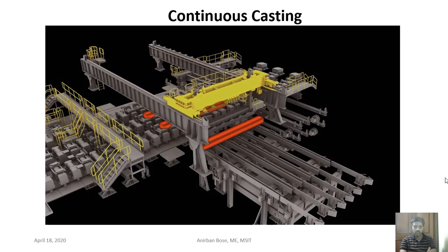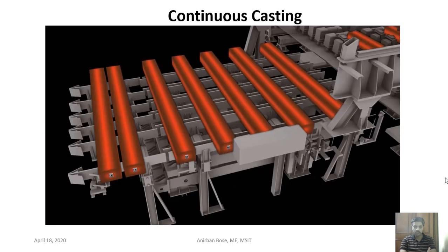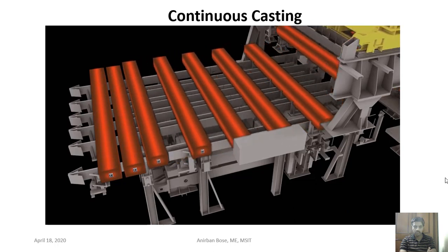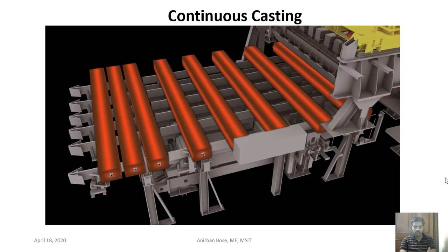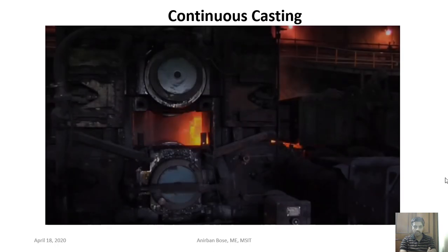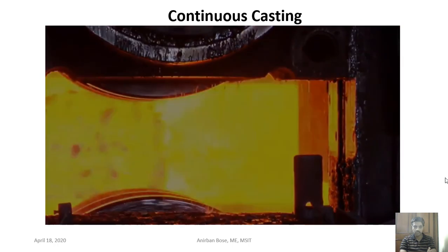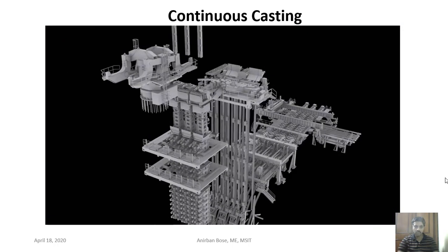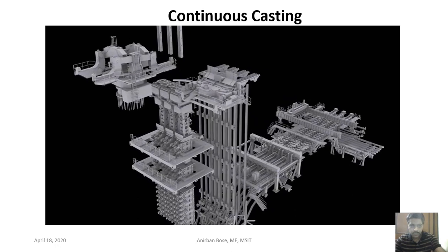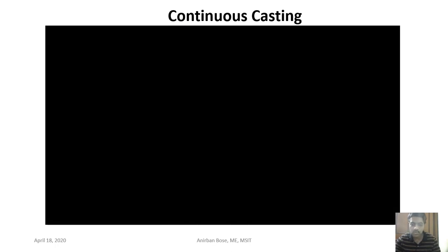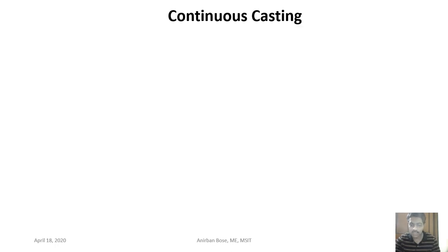On the cooling bed, we weigh each bloom and tag it with a barcode. Finally, we transfer the blooms to a large carrier stand. The bloom then transfers to the rolling mill, where we roll it into bar product. Now you know more about our jumbo vertical bloom caster. So you got an idea about how continuous casting actually happens.